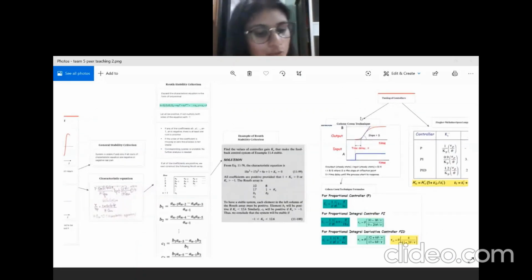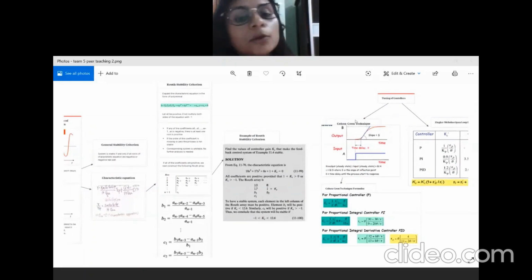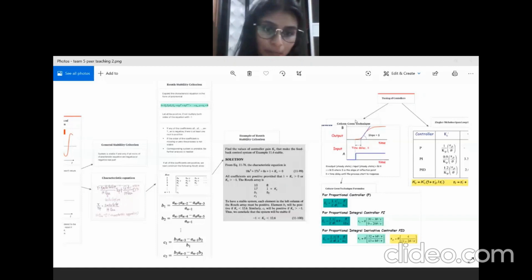First of all, when choosing a tuning strategy for a specific control loop, it is important to match the technique to the control loops and the larger process. Cohen-Coon tuning rules work well on virtually all self-regulating processes, and most control loops such as flow rate, temperature, and pressure are at least to some extent self-regulating.